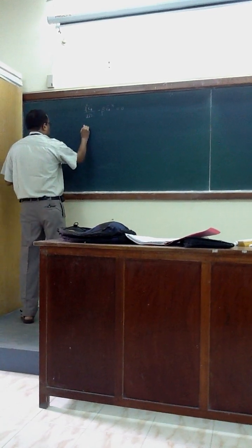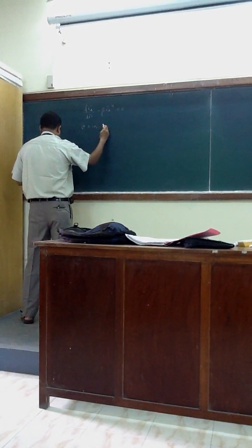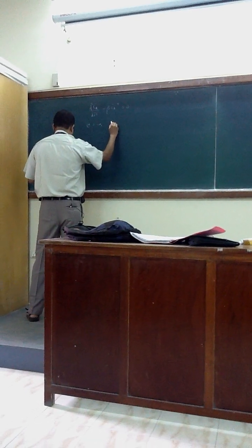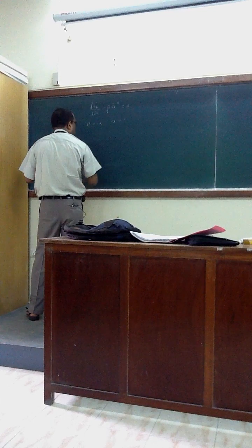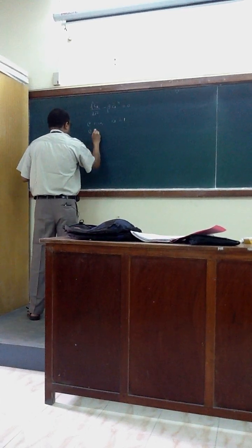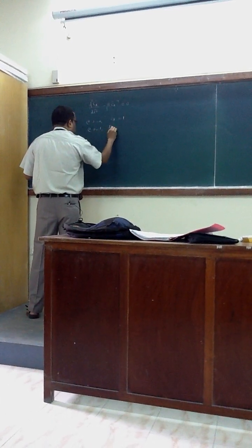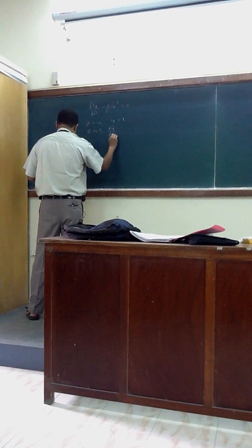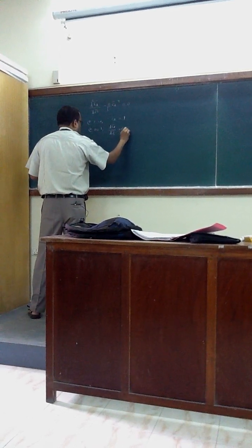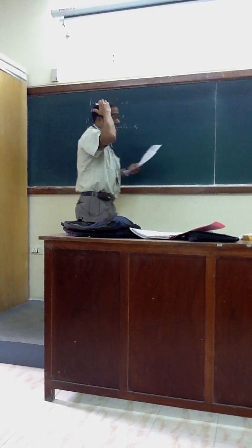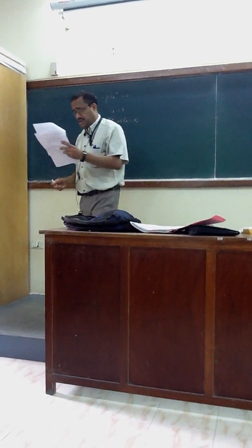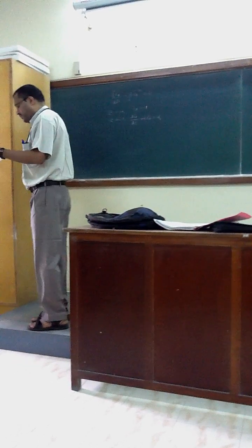Boundary conditions: at z equals 0, we have Ca bar equals something, and at z equals 1, dCa bar by dz bar plus alpha 0 Ca bar equals alpha 1. We got the values of alpha 0 and alpha 1, right? You can get them from the parameters.